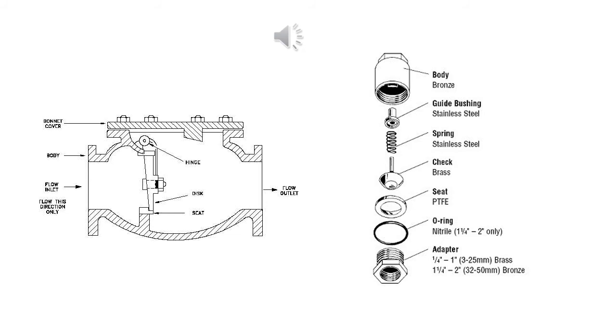As mentioned earlier, unlike on-off valves, check valve internals are flow sensitive. If there is not enough flow, disc movement occurs inside the valve since the disc is always in the flow path. This results in wear and potential for failure.